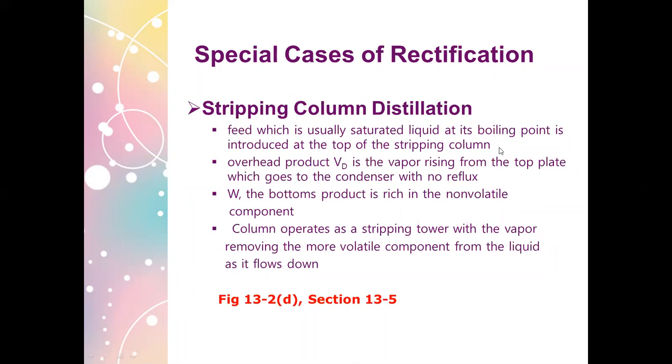So let me read through the bullets in here. The feed, which is usually saturated liquid, normally our feed to the column is saturated liquid, at its boiling point, is introduced at the top of the stripping column. There's no enriching section in your distilling column. You only have a stripping section.